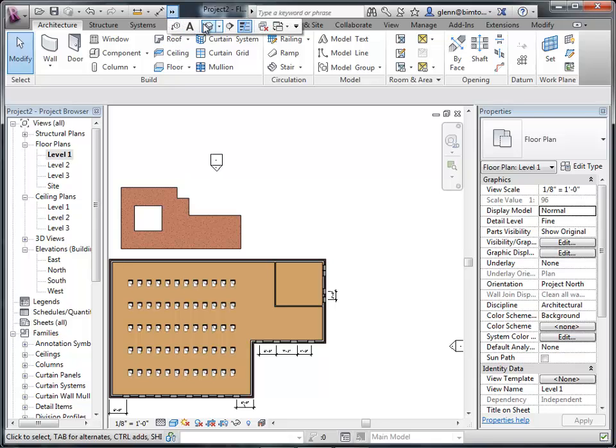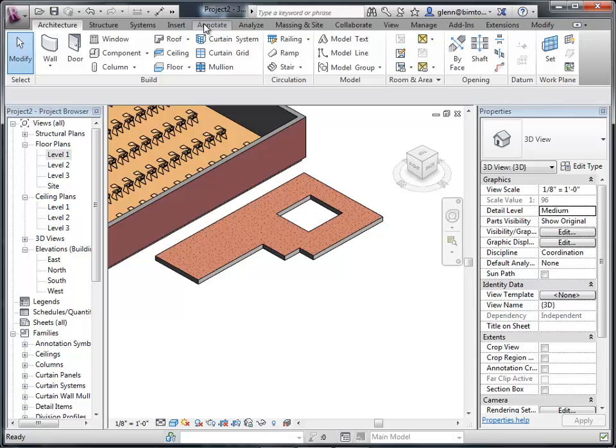Okay, so go ahead, try putting a floor in there, see if you can use the wall definition. One of the few times, and this is where you sometimes get in trouble, is when you're picking walls, if the walls are just a little bit skew or they don't join quite right, sometimes you have to do a little bit of cleanup at the corner just to make that loop continuous. So if you're picking walls and they just miss by an inch or two, just use the trim tool to go ahead and clean up the corners. If you get in trouble anywhere, this is where it is. You pick walls and they don't quite join with each other, and you have to finish joining to make a nice even boundary. But that's all you're driving for, a nice even boundary.